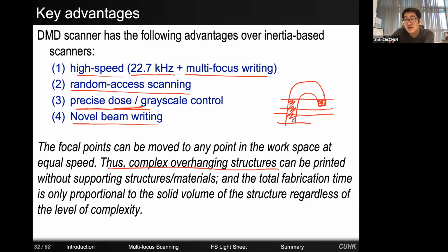Okay. And once liquid is polymerized, becoming solid, the density is going to vary slightly. So if they're not fixed, they can drift away slowly. So in regular 3D printers that you use every day, if you want to write structures like this, you are usually required to print a sacrificial material, a supporting structure. And after your printing is done, then you cut this off.